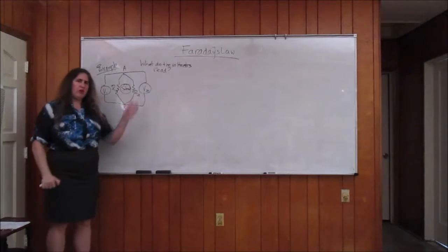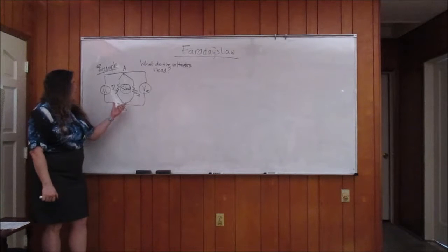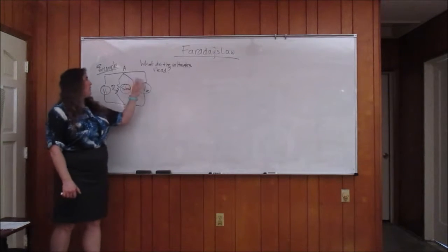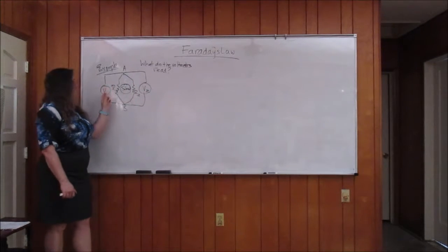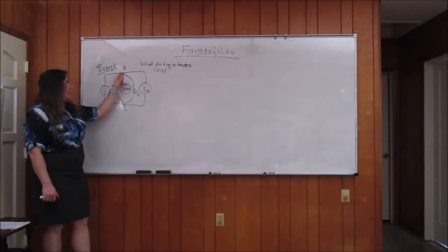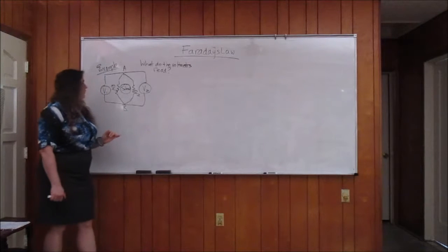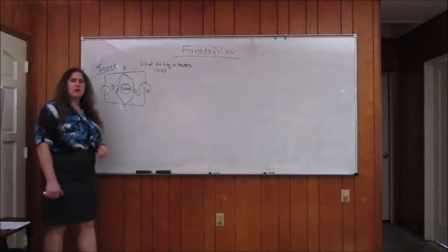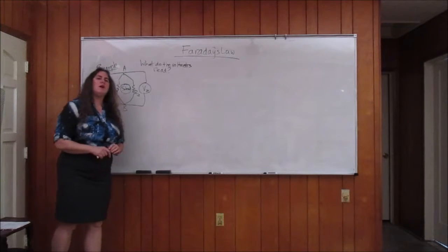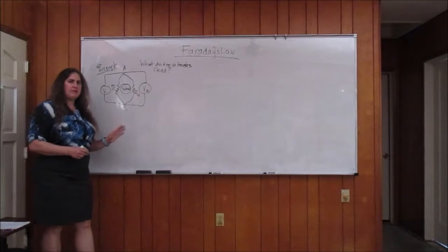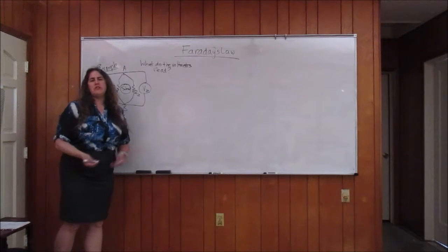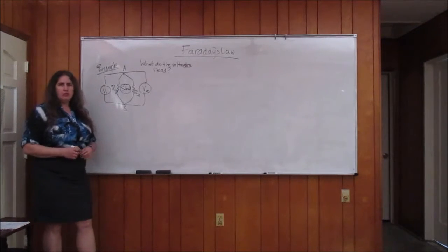If you just shout out an answer right away, it might be that, obviously, because the voltmeters are connected across the same points in the circuit, they have to have the same reading. And that's completely wrong. The reason you might be tempted to say something like that is because you get into the mindset of using Kirchhoff's loop rules.